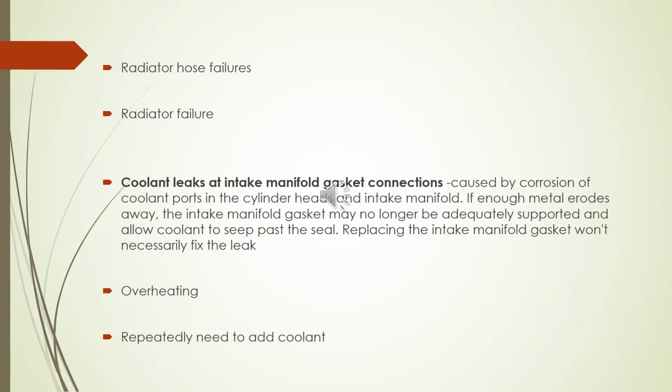We are still discussing the symptoms of electrolysis corrosion. Radiator hose failures or radiator failure. You find blockages on the radiator and extreme rusting. Coolant leaks at the intake manifold gasket connections.